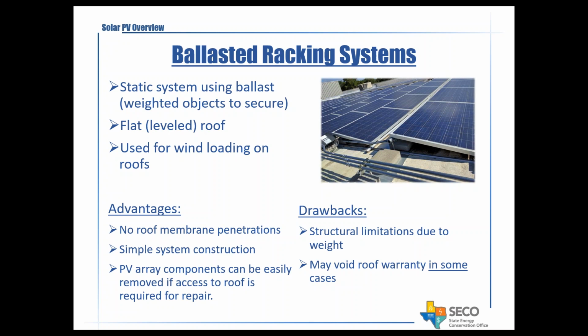Some of the drawbacks are that there's potentially structural limitations due to the additional weight of these systems compared to other types of systems, due to the nature of having additional weights to hold them down. In this graphic on the top right, you'll see that there's concrete blocks used to hold the systems down. That's primarily for wind loading requirements. And in some cases, you may need to consult the roof warranty just to make sure that it doesn't affect the warranty on the roofs.